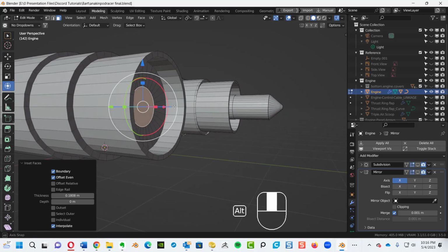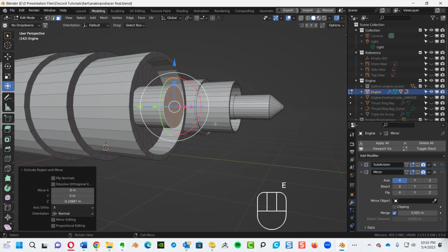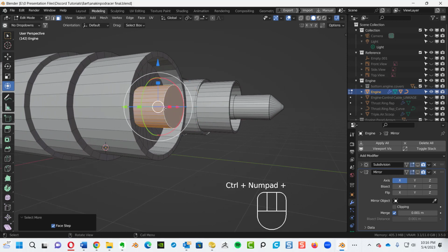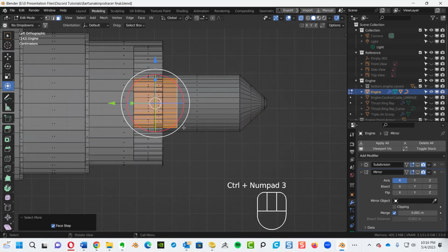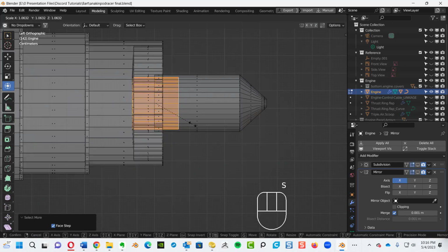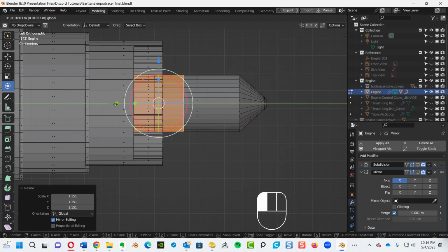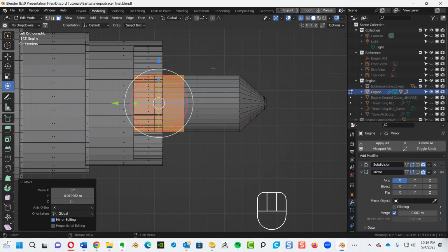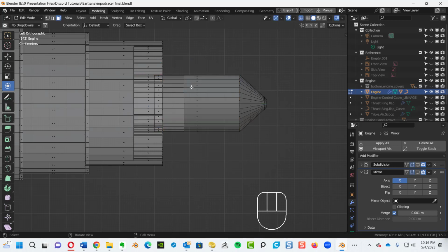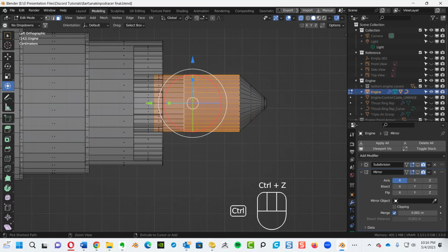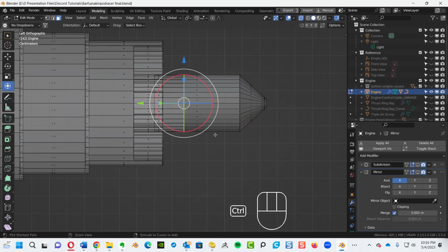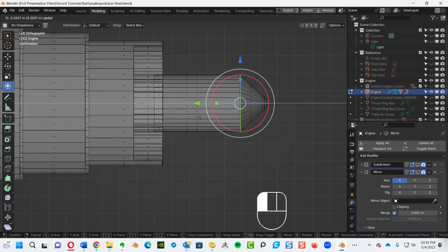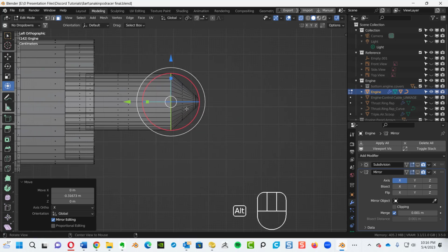I'm not sure if the shape is accurate, so I'm going to Control plus again. It's like that entire thing. X-ray view. Let's go back to the side. Alright, so it's a little too big. No big deal. Just hit the S key and just scale on up like so. And if it pushes in the back a little bit, then just flatten it out like so. Go grab that. Let's do this. Control, deselect those edges, place that on right about there. Okay, just about there, right?